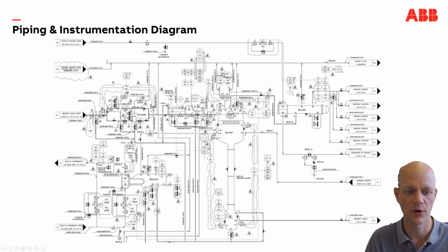So it shows a number of the pipes in the plant, and then also the instrumentation in the sense of the controllers, the sensors and the actuators that are in such a plant. And in this diagram we see, for example, a tank or kind of a reactor where some substances are mixed, and we see some heat exchangers to heat up or cool some fluids. And then all these little circles in the picture are actually sensors. And there are also actuators visualized, like valves, for example.